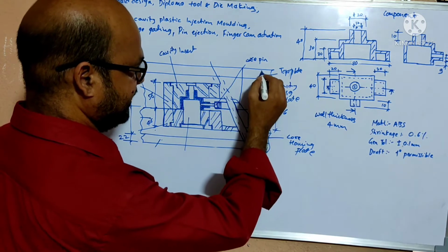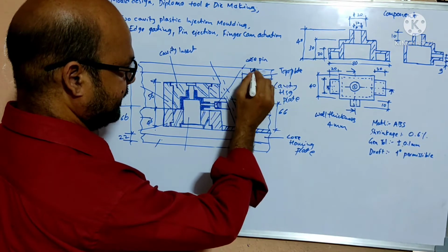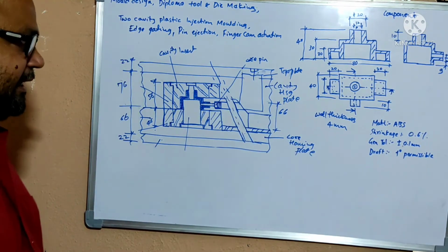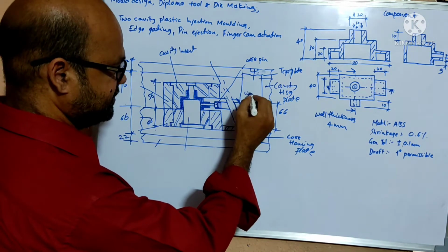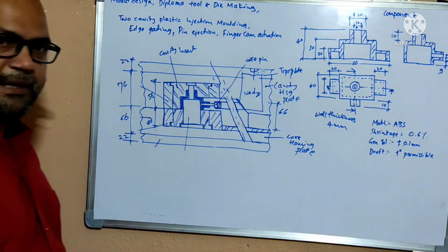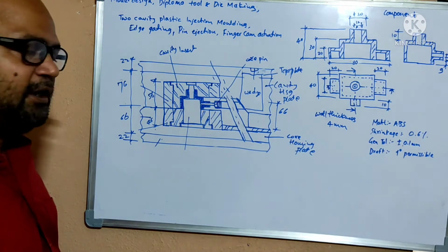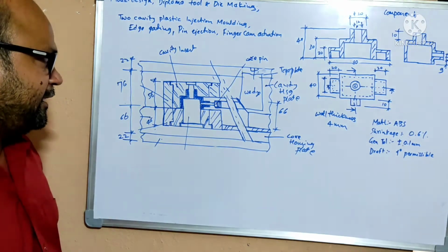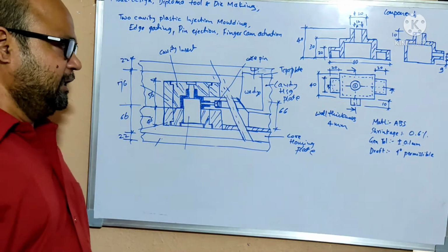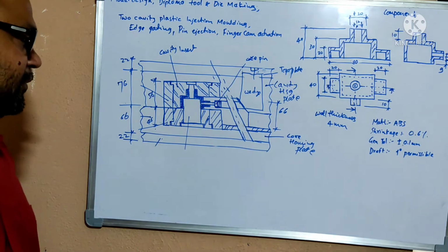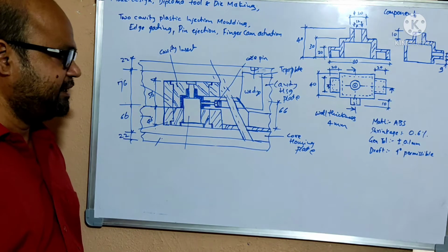This one is the wedge. You are going to place it in the top plate, and this is the main wedge. This is the main insert, the main element of the tool, which locks the side core and keeps it from coming out of the tool during the force of the molten metal entering the cavity.